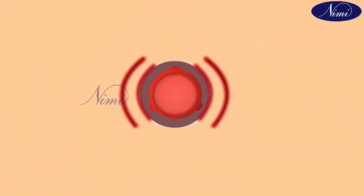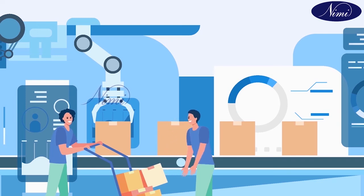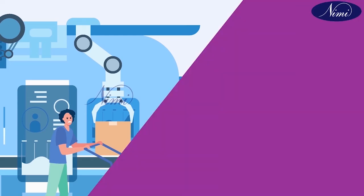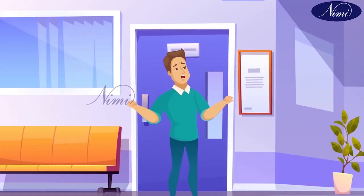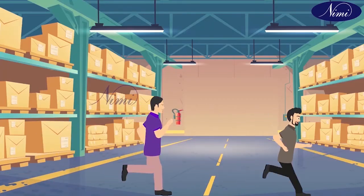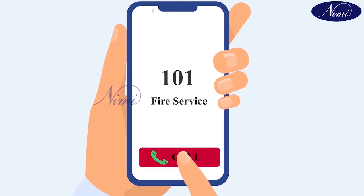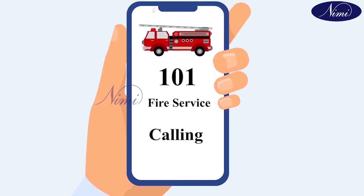It is important to understand the basics of how fire occurs and how fire behaves inside a building. First, raise an alarm and alert the people around by shouting fire, fire, fire when you observe the fire. We have to alert everyone by raising an alarm signal so that everyone is able to escape from the fire. Next, inform the fire service immediately.